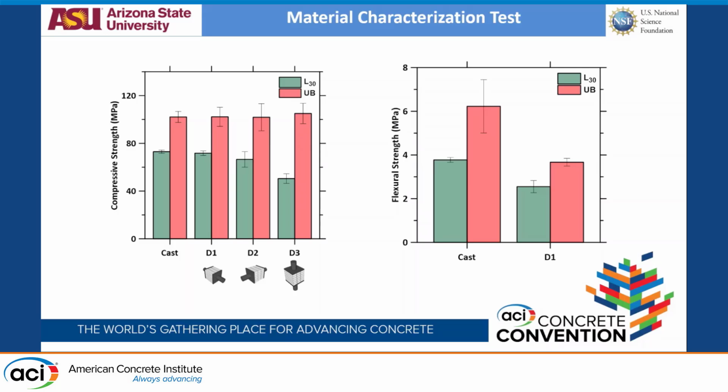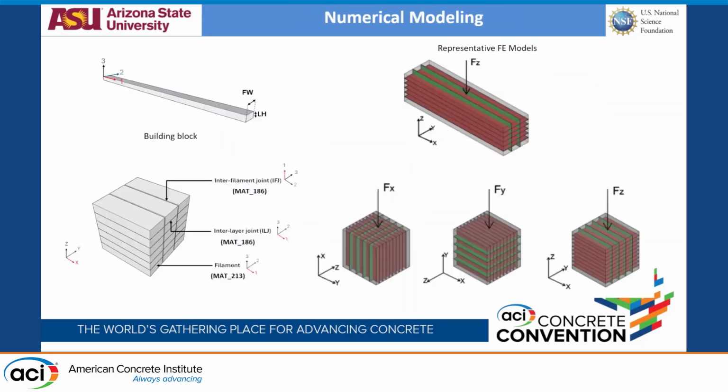Again, this could have other applications, in the sense of, do you want to do a lower water cement ratio, higher SP mix so that you don't get much of an orthotropic or anisotropic nature? That could be another thing of study. But in terms of flexure also, the typical thing that we see is the cast samples performing better than the printed samples. I'll use this for validation, so I'm just showing the results here for the moment.